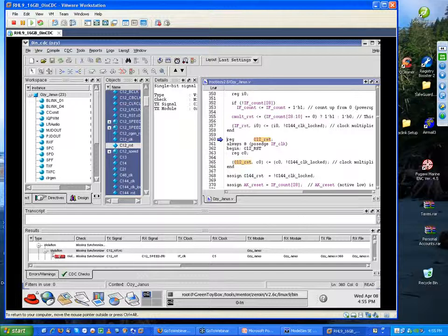Okay, so I had this violation here, and it said missing synchronizer. So, is this the one? Yeah, this is the one. So I got to looking. I was like, okay, here I'm creating this reset. And I've just started going through the code and doing more cleanup where I'm starting to put these prefixes on my signal names, and I suggest doing that.